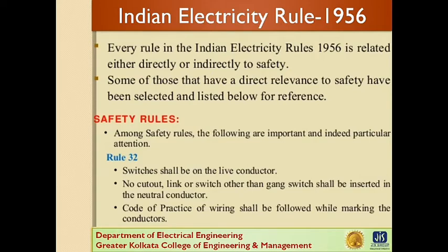Safety rules. Among safety rules, the following are important and deserve particular attention. Rule 32. Switches shall be on the live conductor. No cutout, link or switch other than gang switch shall be inserted in the neutral conductor. Code of practice of wiring shall be followed while marking the conductors.